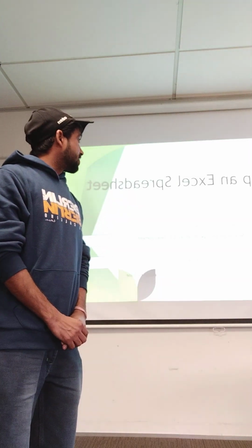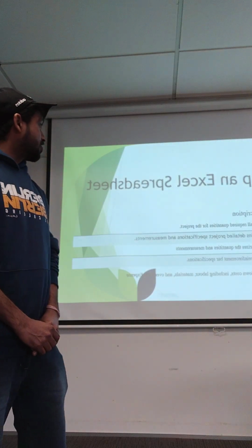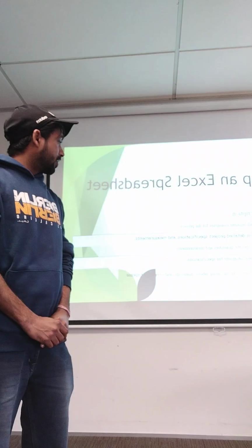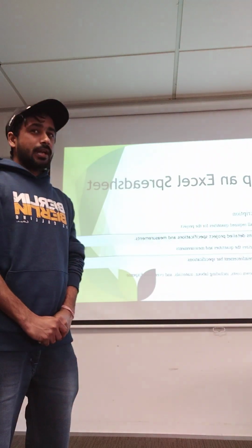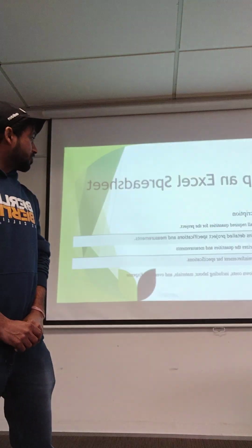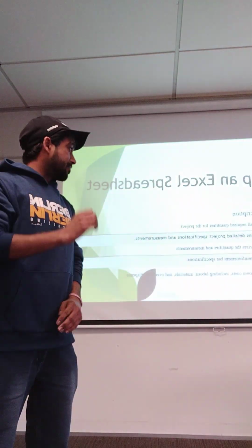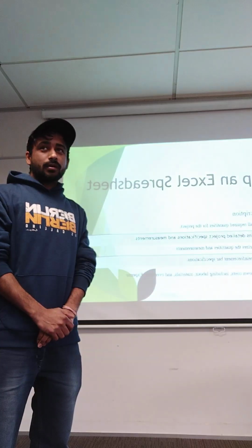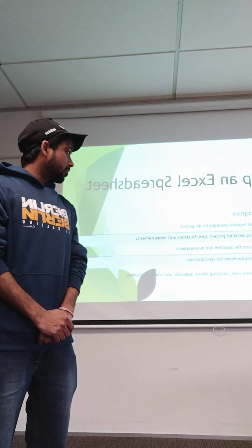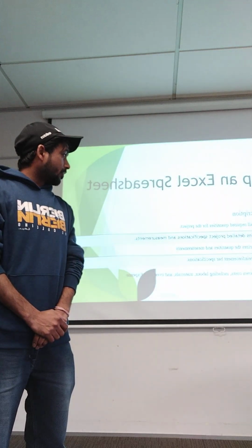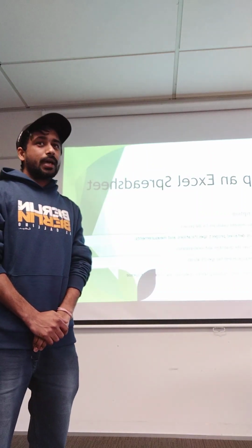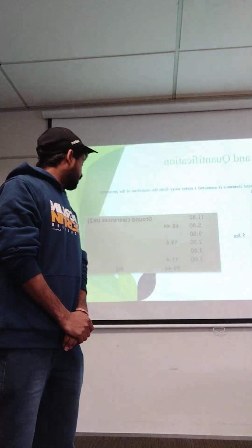My next sheet is setting up the separate sheets and their description. Schedule of quantities lists all the required quantities for the project. TDS is the standard data sheet, which contains detailed project specifications. Then measurement and abstract, and detailed reinforcement about the bar reinforcement in our project according to the drawing, and the bar schedule and rate build-up, which break down the cost including labor, material and overhead expenses.